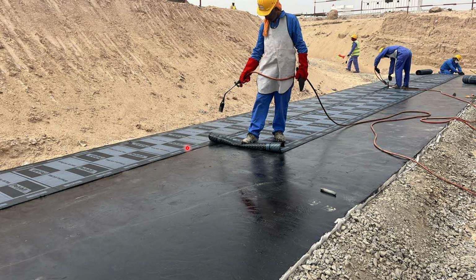So this is actually the horizontal lap. Vertical lap is when we terminate one roll, like for example this roll finishes this area, and then we have to start another roll. In such cases this is called a vertical lap, and usually we provide 15 centimeters, but it also depends on the manufacturer. Whatever they provide in their data sheet, we have to follow that for horizontal lap and vertical lap.